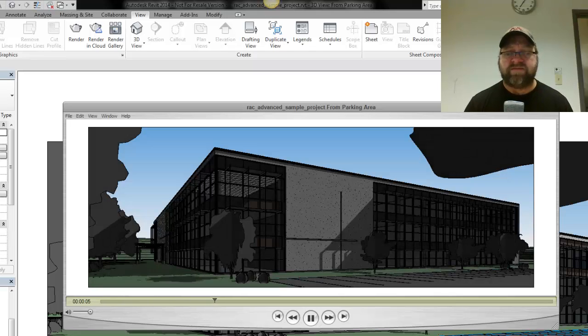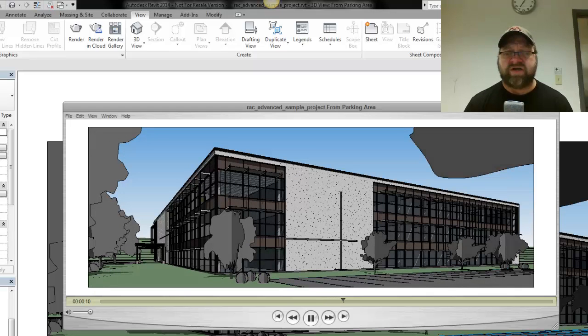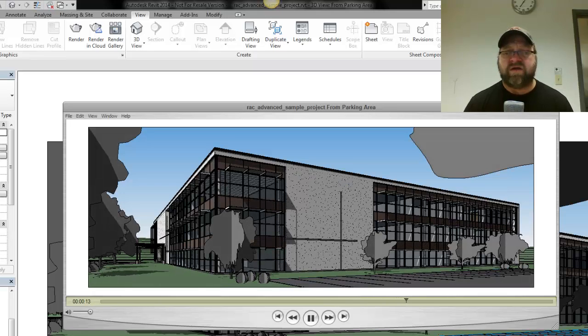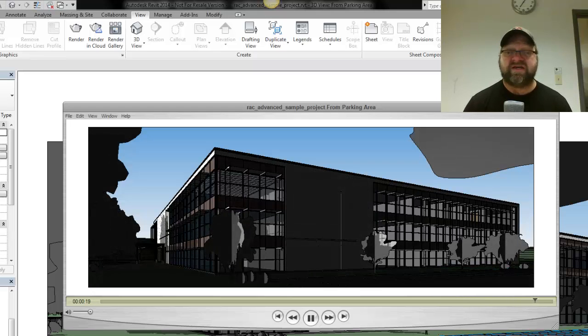So you see the sun coming up, and now you see the shadows moving across the building, and you can see the sunshades come right to the underside of the sill and then back down. So we know that we provided shade for this building during the whole day, at least on that particular day. And I think this was probably set at a solstice. We know that that's the highest point in the sky for the sun, so that's what we need to protect against. So anyhow, that's one example of how we can capture time within our model, by using some type of solar study, and we set a time range that we want to look at.